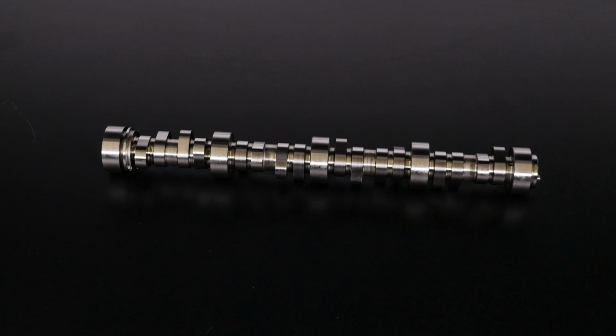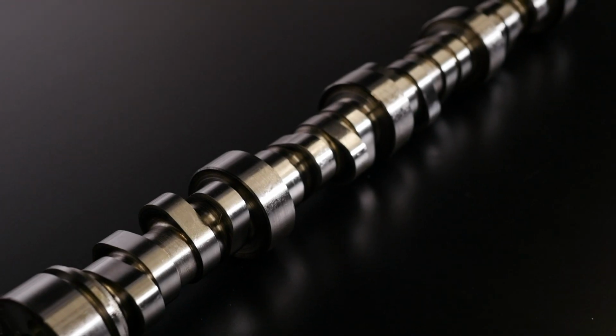However, the factory cam in the GM LS V8 is pretty pathetic. Swap in a decent cam with a bit more duration and a bit more lift, and you're going to find that all of a sudden, by the factory rev limit of 6,000 RPM, the power and torque is still increasing. Well, at least the power is still increasing. Our torque's probably starting to plateau at that point and fall away. So what this means is that now, if we rev the engine further, we can potentially make more power, and it's all dependent on the cam.